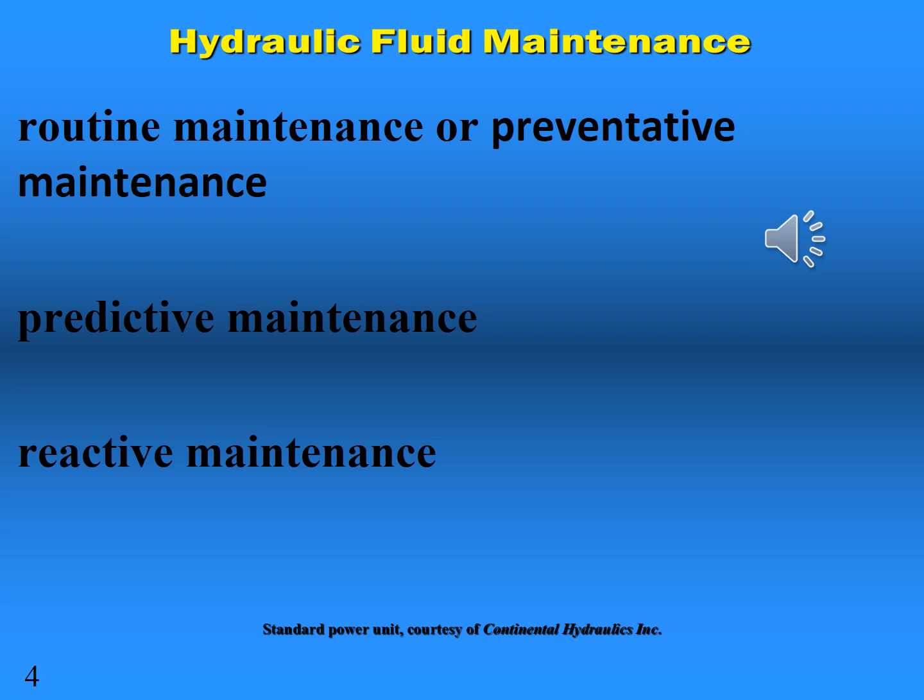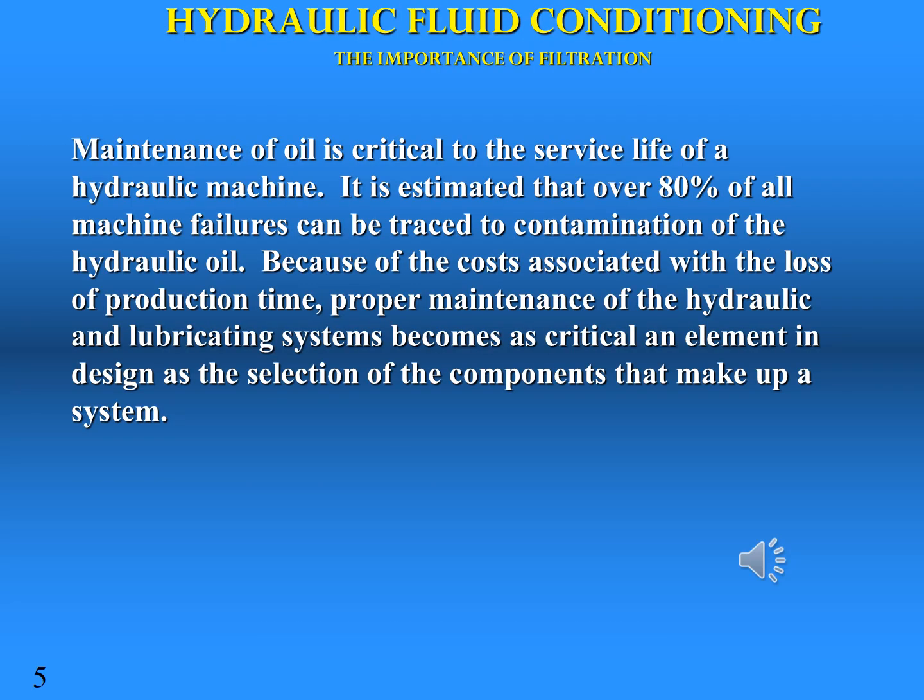We will begin by discussing the origin and nature of contamination along with its effect on system operation. Hydraulic oil circulates through the system, contacting the surfaces of all moving parts, providing lubrication as well as other functions. It only stands to reason that contamination in the form of surface wear, pollutants, and degradation of the oil will occur. When a failure does happen, it is critical that the hydraulic system be thoroughly cleaned so that any residual contamination does not cause repeat failure.